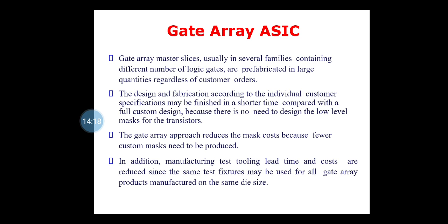The gate array approach reduces the mask cost because fewer custom masks need to be produced. In addition, manufacturing, testing, tool lead time and costs are reduced since the same test fixtures may be used for all gate array products manufactured on the same die size.